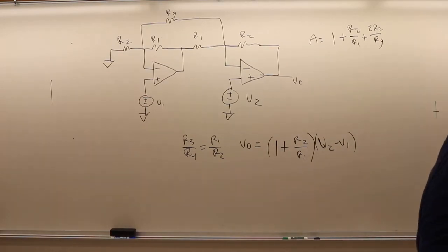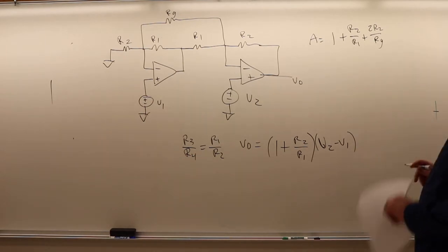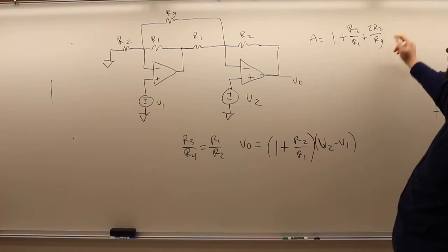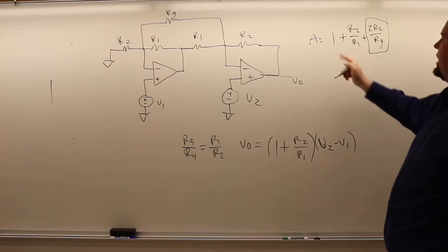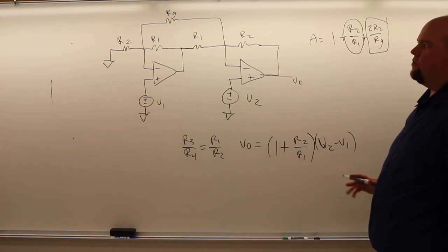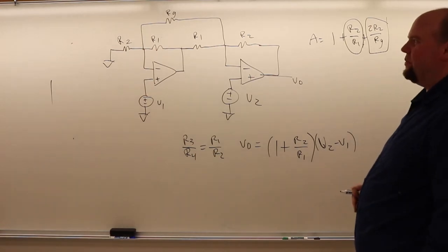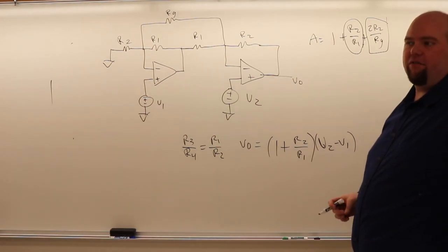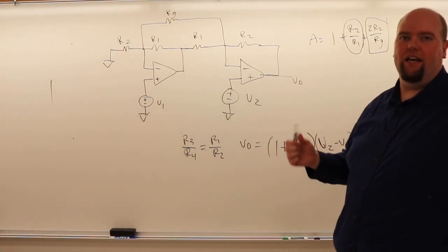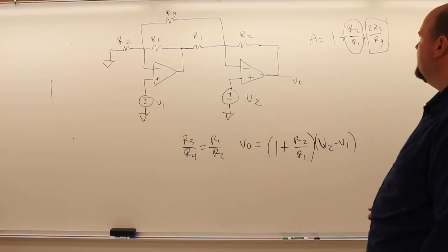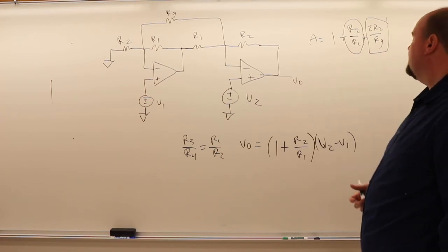What's the downside of this? What makes this less ideal than in the previous case? This is highly nonlinear, especially if this ratio R2 over R1 is not small. It's similar to what we had before, 2 R2 over RG, but instead of having 1 plus this ratio, we now have 1 plus this component plus the ratio. So it can create a slightly more wonky gain curve, but the reality is it wasn't super clean to begin with. The old version wasn't super clean either. Ultimately, what you do is look up a table, and most manufacturers would have explicit values of gains that people would use. So it would say, if you want a gain of 1,000, use this value, 100, use this value, 10, use this value. Typically, they're pre-calculated for you, in which case it's not that big of a deal. Even having this extra term here doesn't really matter too much.